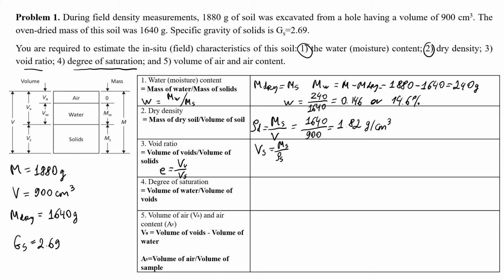When we talk about density of solids, we should most likely use specific gravity, because specific gravity has density of solids in its definition, as shown here, and then it will lead to the formula as density of solids equals specific gravity times density of water, and this will take us to volume of solids equals mass of solids divided by specific gravity and density of water.